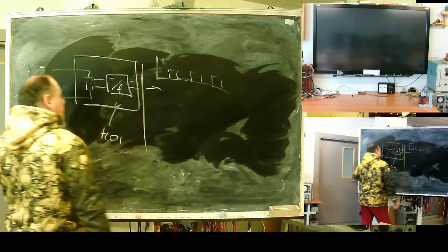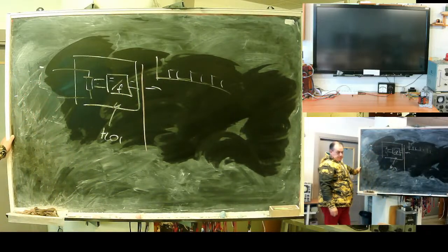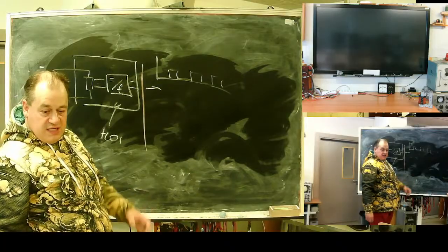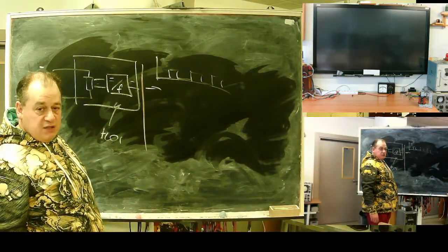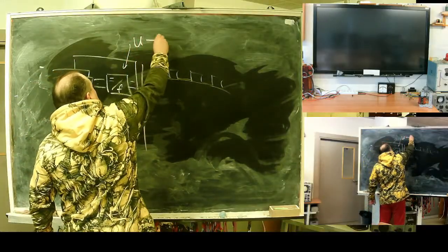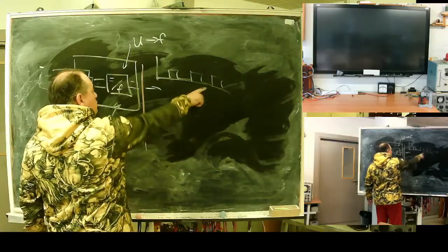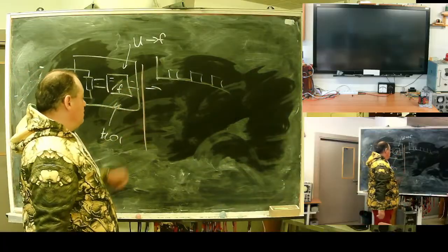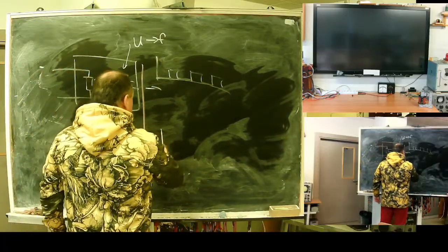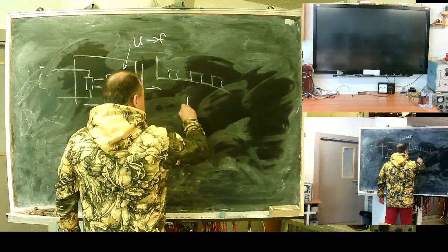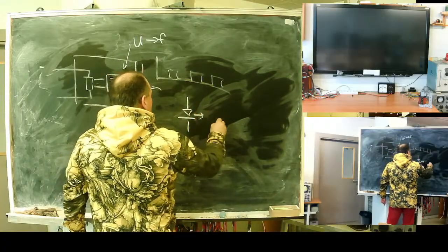It's very typical to the auto industry, aviation industry, when an analog signal, for example airflow, is converted into pulse frequency. This is a voltage to frequency converter. Pulse frequency is a function of voltage. And pulses go from hot to ground potential, for example, with a simple optocoupler.